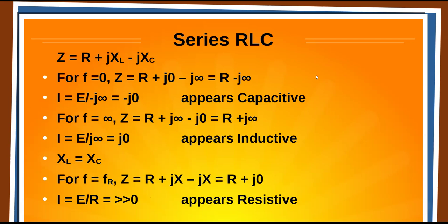Because in a series circuit, remember, it's high impedance and essentially zero impedance at resonance. So that's where you get maximum current, at resonance. It's limited by the series resistance, so it'll never be less impedance than whatever the resistance is.